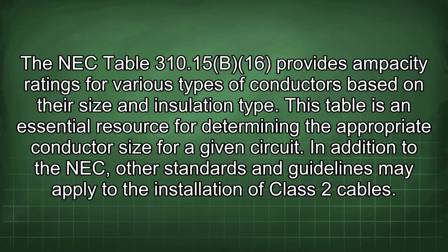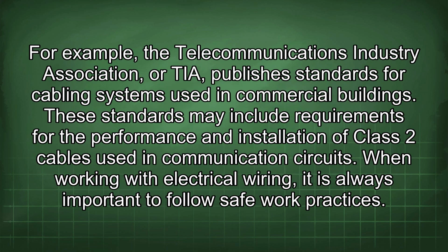In addition to the NEC, other standards and guidelines may apply to the installation of Class 2 cables. For example, the Telecommunications Industry Association, or TIA, publishes standards for cabling systems used in commercial buildings. These standards may include requirements for the performance and installation of Class 2 cables used in communication circuits.